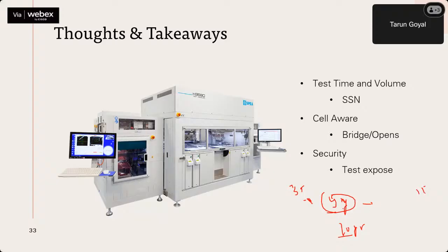But even if we have zero DPPM when we are shipping, after 3 or 4 years this car may have manufacturing latent defects which start slowing the transistor, and then it malfunctions. We call these zero defects, ZD.